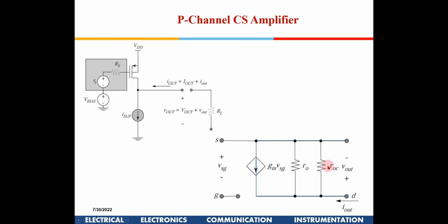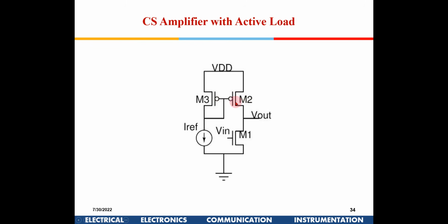10 mega ohm parallel with 10 mega ohm will give you say 5 mega ohms. So you will get higher gain. So that is the flexibility. By using active load, your R will be very high, so you will get higher gains in this case. The gain will be higher, and to set the operating point also it will be easier. Yes, sir. How to set the operating point?